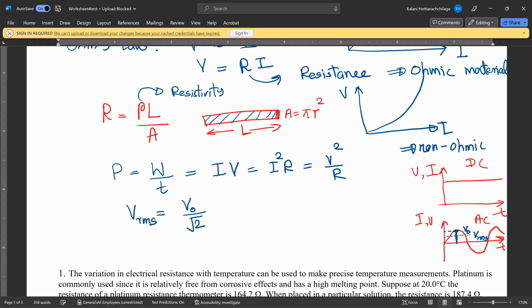So this V_RMS value you measure by using a multimeter, but the real value of the circuit is, you see that it keeps changing, that will be your peak voltage, which you will be able to measure by using the whole signal. You will be able to measure it by using an oscilloscope in the laboratory.